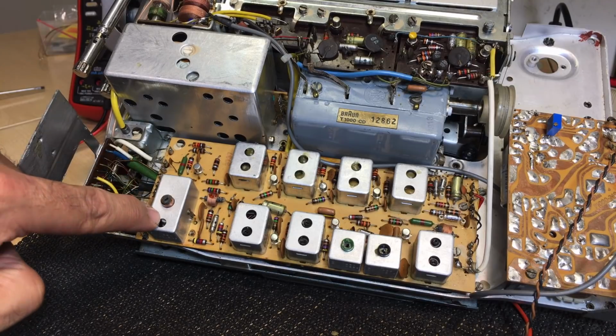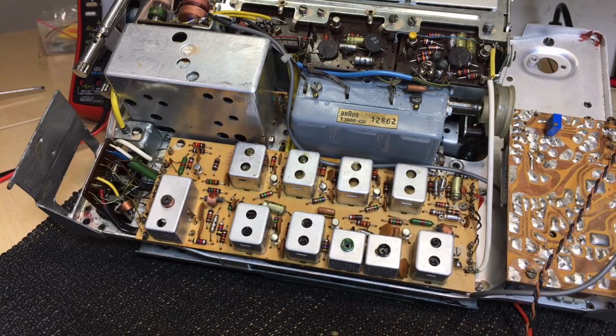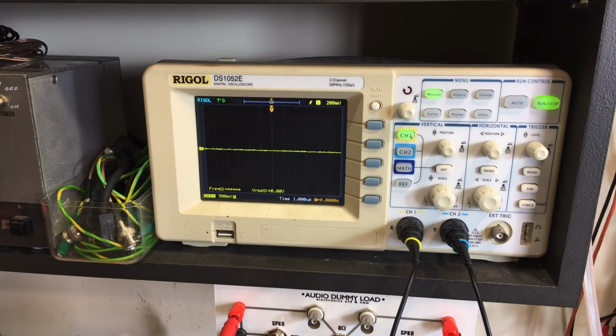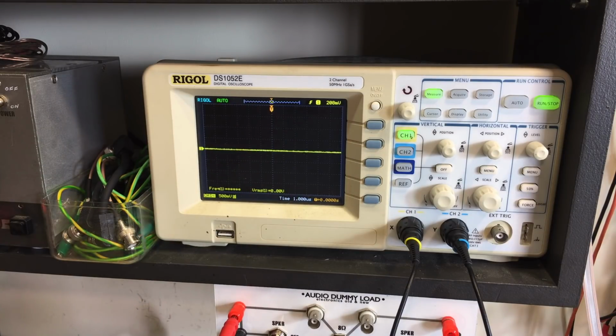So we should get a 455 kilohertz or thereabouts signal from this. And what we're getting is rather strange. Let me show you. Now when I switch on the BFO, this is what happens. It tries to oscillate, it comes on, and then it just dies. Off, switch on the BFO, and the frequency I can see is around 450, but I just need to adjust that core. So our BFO is failing to stay on.